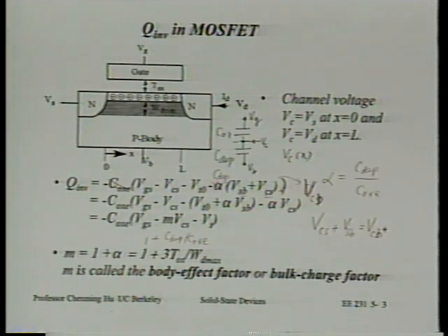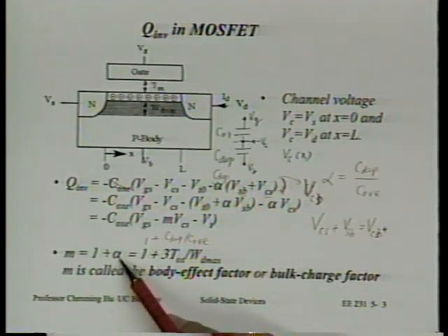That is considered a bad design for a transistor because it actually hurts our transistor current. We will see that pretty soon. That's why I want to carry it. On the other hand, it's considered a very good design for the short channel effect. So we're always going to be dealing with this trade-off. Today, it seems we can perhaps take an alpha of 0.2, which may be sufficient for the short channel effect, and we may have to deal with a little larger alpha in the future.